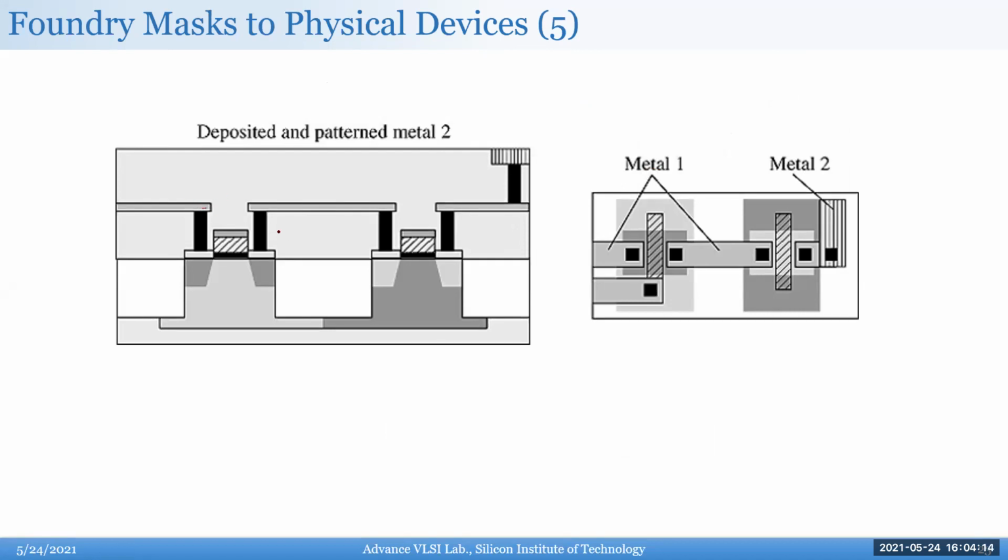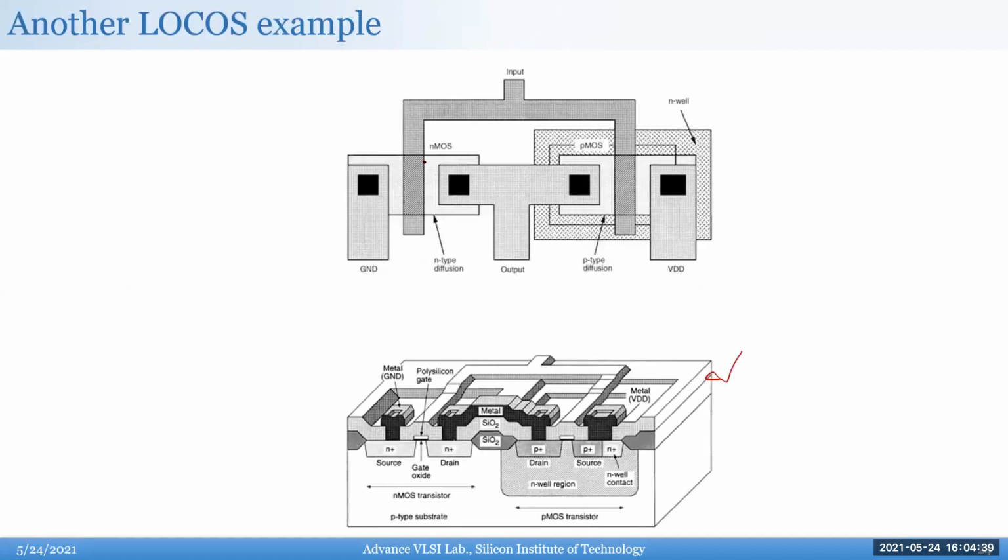So then you go to the top level metal. This is showing metal 2, your next level of metal layer. So you again take the mask. Before you do that, obviously you do the same thing: you do the isolation from the next stage using silicon dioxide, and then do metal 2 here, and do the routing using the same patterning process and so on.